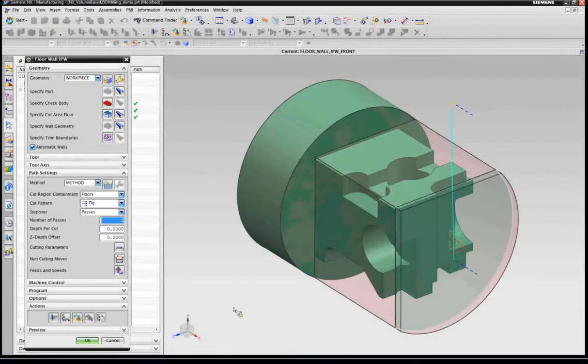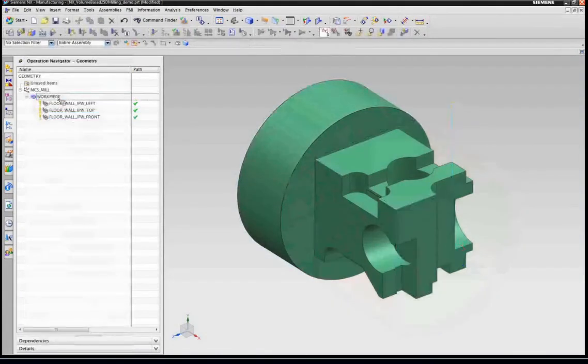Initially, when we were testing this new version, I was very scared because it stops in the middle. And I'm like, it's not even cutting the entire part. This is a bug. But you'll see later on that this is just our attempt to really minimize air cutting. When the tool reaches that point, it has cut all the material. It's a big tool, remember. It's got all the material that there is to cut on this face, and it can retract. It's done. And we'll see that later. So that's my 3rd operation.